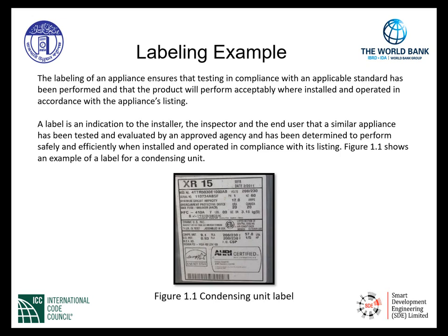We have the model number of the condensing unit, the serial number, the manufacturer date, the voltage, the phase, the hertz, which is cycles per second, the minimum circuit ampacity, the overcurrent protection device, the maximum fuse size, and the type of refrigerant that the condenser uses.